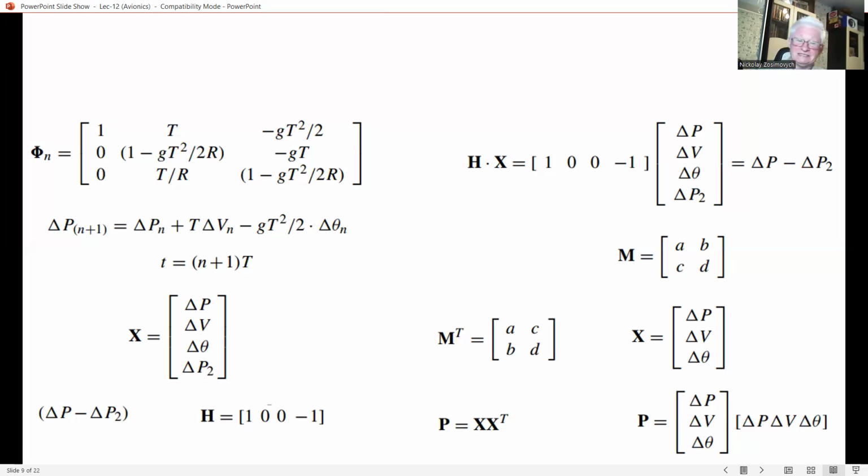The 19 state model comprises the following error states: 2 horizontal position errors, 2 horizontal velocity errors, 3 attitude errors, 3 gyro biases, 3 gyro scale factor errors, 3 accelerometer bias errors, and 3 accelerometer scale factor errors. I hope you understand why we use 3 in all three directions on the position.